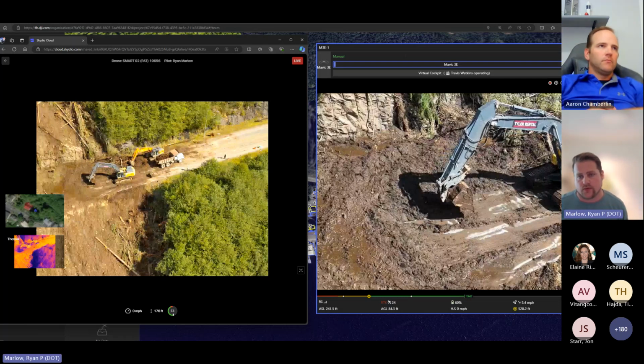Yeah, the airworthiness review, that's been an interesting item. A lot of these docks have cameras inbound, so when they come in and come out, we can inspect them. That is a current workflow, I believe, in Part 107, as well as our maintenance plans, but also an item that we're watching very closely is just what the current wear and tear is on these systems remotely. When batteries get switched out, I know that's been a big one for us, is we switch out our batteries basically every 8 months with the docks, just due to them constantly being plugged in and charging. But those are all items that we're working out as we go with a lot of the standardization with dock deployment. I don't know, Aaron, what are you guys seeing with your docks?